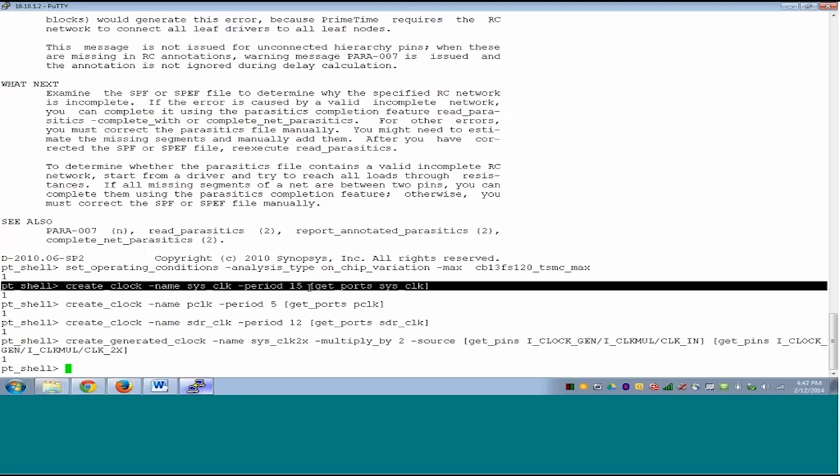Secondly, you can see what source they might be coming from. Typically, if you are working at a chip level, and two clocks are coming from the outside world, most probably they will be asynchronous. Why? Because engineers want to limit the routing resources, especially for high frequency signals like clock.